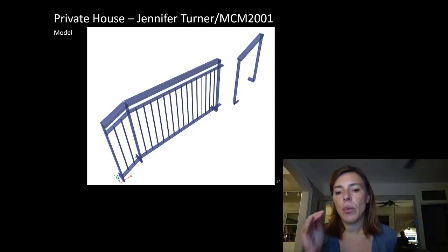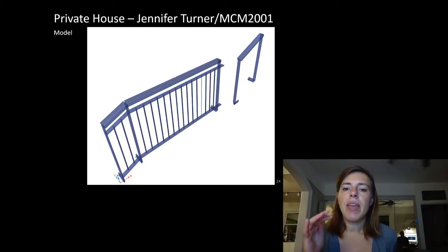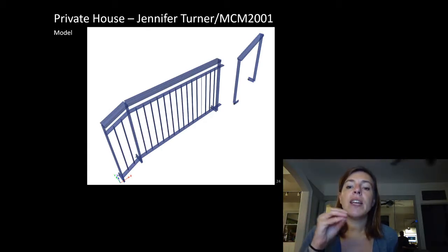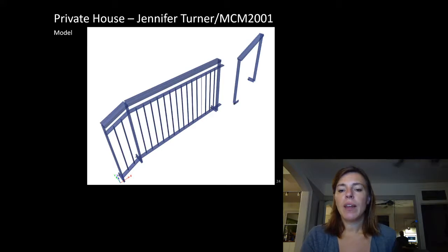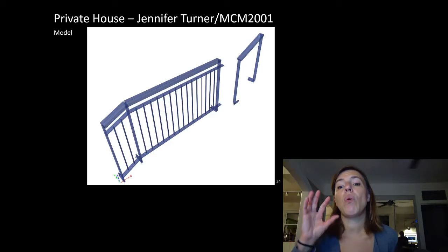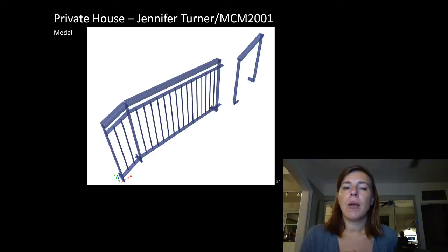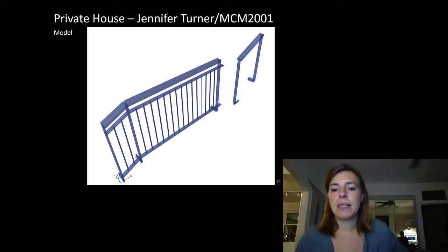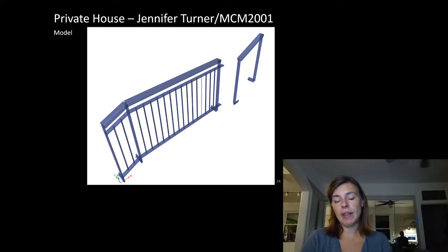Again, I start with the premise that it's a guard, even if it's not, and then I look to see if it doesn't work for what they're showing. And if it doesn't work, then I might go down to the handrail design. Mostly because it's nice to say, should they change their mind or the building department come back and say this needs to be a guard, my sign and stamp still works for it. If it doesn't, we would have to explicitly state that it's only a handrail on the drawings. This kind of gives, for no extra cost, the architect some freedom.